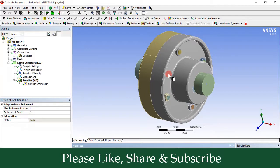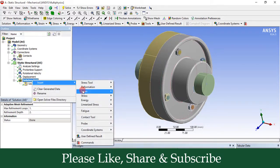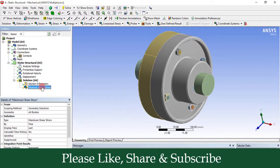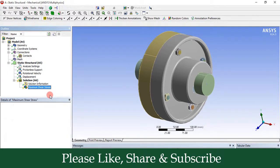Now the solution of this model is obtained. So let us right click on this solution in order to check the output parameters. So as I have said, this coupling is subjected to a rotational velocity, which results into the shear stress. So shear stress will induce in this coupling. So let us focus on the shear stress for this model. So right click on solution, go to the stress, go to the maximum shear stress, right click on this maximum shear stress and click on evaluate all results.